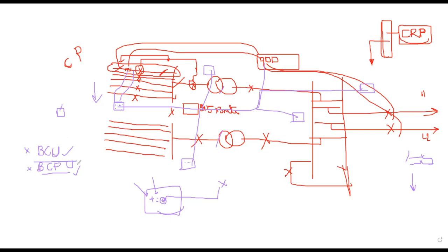Now, all the developers across the globe are going with the BCPU, so the size of the relay panel has decreased. For the 33 kV, mostly we implement only overcurrent and earth fault protections, so this is already coming in the BCPU.